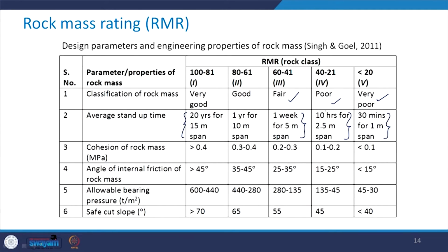So although here you have 10 hours for this 2.5 meter span, you should not wait till 9 hours and then only go for the installation of the support system, because in those 9 hours the rock mass quality after excavation will deteriorate, and ultimately the effective average stand up time may not be this 10 hours for 2.5 meter span. So we have to be careful about this.